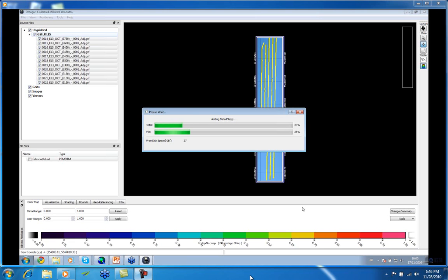I did have one question. How, and procedurally, does CUBE deal with uncompensated motion, especially roll? It treats it as being... the problem with something like that is that CUBE is not going to back out any motion artifacts in the data. It doesn't. It will show you where you've got them because the uncertainty will be higher, but it won't actually back those out. You have to do that before you bring them in here.